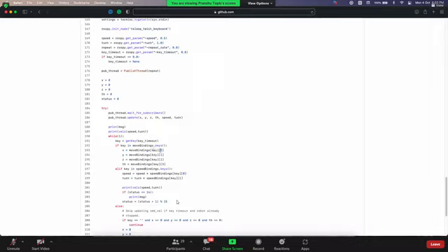it takes the 0, 1, 2, 3 values. It takes X, Y, Z, TH. So X is linear velocity in the X direction, Y is linear velocity in the Y direction, Z is linear velocity in the Z direction. Usually we don't need these two, but TH is theta. Theta is the angular rotation. So if you want your robot to move left and right, you need the angular thing, right? So it takes these things.